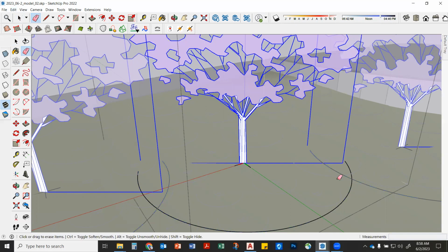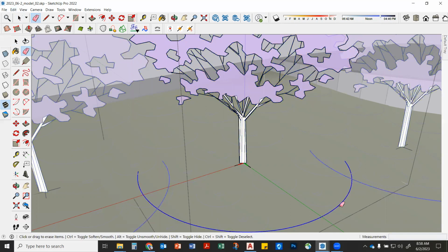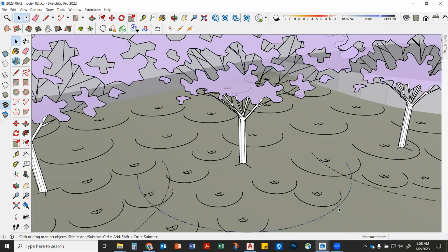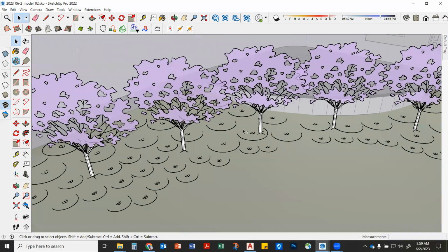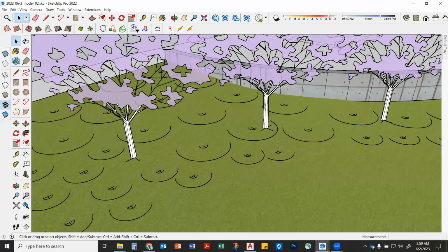There's two ways of erasing in SketchUp, right? You can delete it with an eraser. Well, the other option is you hold down Shift and while you're holding down Shift, you erase and it just hides it. Okay. So if I turn off view hidden geometry, you don't even see it, right? Look. Oh, right. All right, now there's another way too.